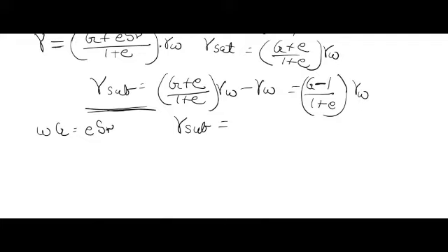In this case, water content is given as 40%, and this is at saturation level, that means at S_r equal to 1. And we know G, so we can find e, that is 0.4 into 2.7. That's the way we find e, the void ratio.